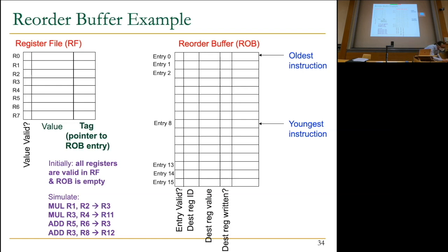So let me go back over here again. Sorry for this frequent back and forth, but basically this says 2. What do you do? While decoding this latest instruction, you take this address 2, index the reorder buffer, just like a random access memory, meaning not a content addressable search, and get the value if it's available over there. Otherwise, you'll stall until the value becomes available. Right? Basically, this turns the reorder buffer from a CAM, content addressable memory, into a RAM, which is simpler, at the expense of some indirection, since you have to go through the register file first.